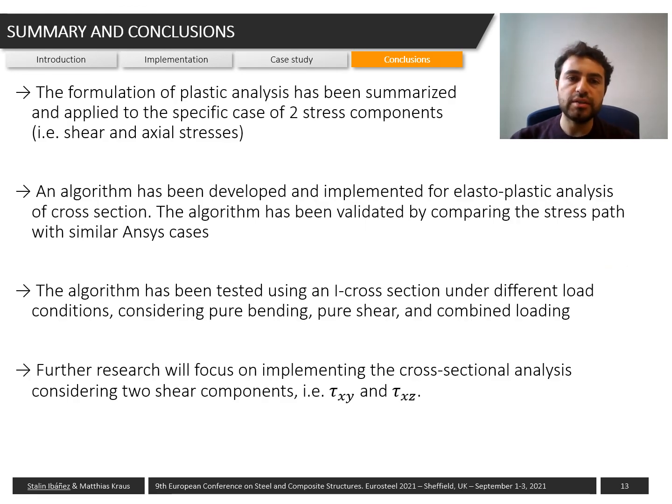As a summary, the plastic formulation has been implemented for the specific case of two stress components, shear and axial stresses. The algorithm has been developed and implemented for elastoplastic analysis in the cross-section, and this has been validated in comparison to commercial software.